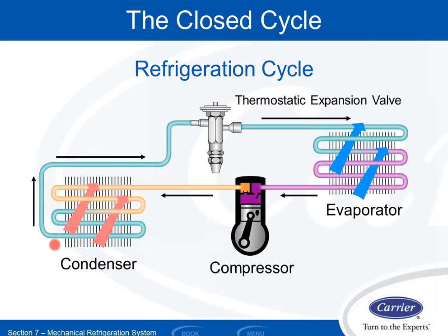So my condenser coil is sitting outside my yard and at my house. My evaporator coil is sitting above my furnace, right? Those guys are the yin and yang of each other. And by the way, the names evaporator and condenser, those come from what the refrigerant's doing inside there. They don't come from what the air is doing on the outside. The air is actually doing the opposite, right?